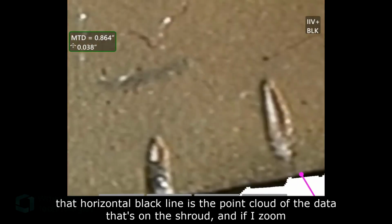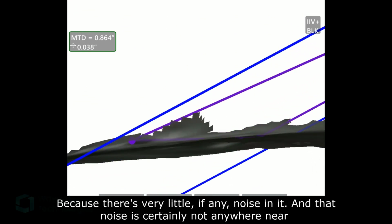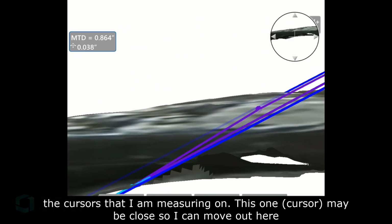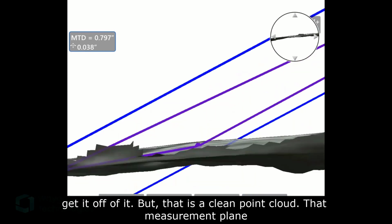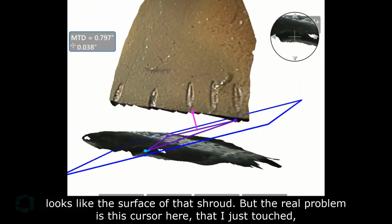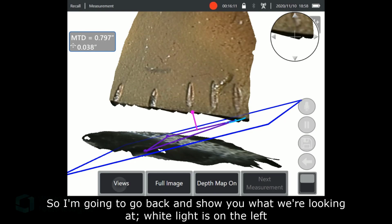And if I zoom significantly in on it and pull it up on the screen with 2 fingers, this is indicative of what I call a clean point cloud, because there is very little, if any, noise in it, and that noise is certainly not anywhere near the cursors that I'm measuring on. This one may be close, so I can move it out here, get it off of it, but that is a clean point cloud. That measurement plane looks like the surface of that shroud. But the real problem is this cursor here that I just touched and made active is on the blade and not on the shroud. So I'm going to go back and show you what we're looking at.